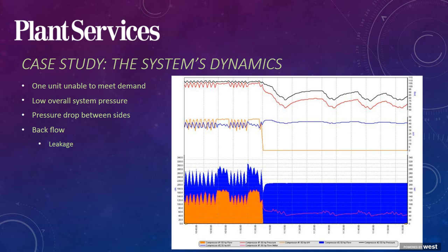This suggests that a significant portion of the air demand in room number 1 was actually air leakage. Also note that with both compressors online and loaded, pressure is maintained well above that 95 requirement. However, the average flow is typically below the flow for the 60 horsepower.